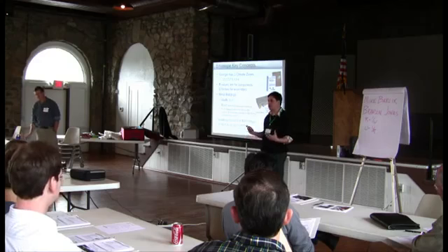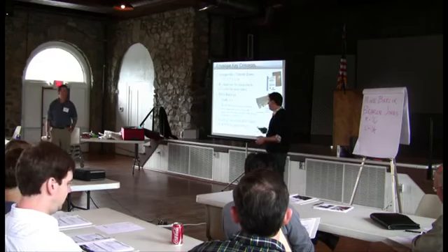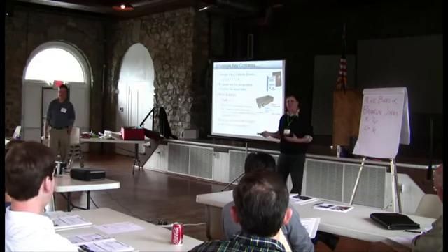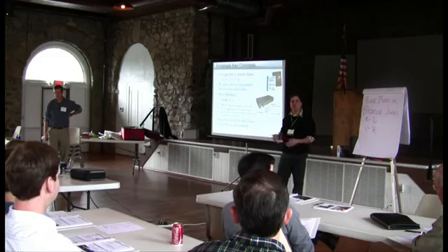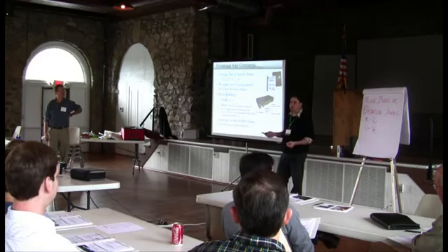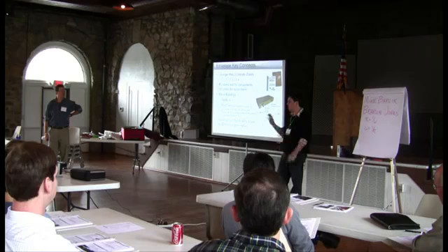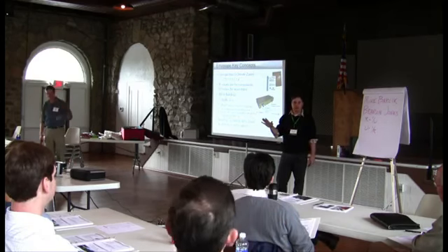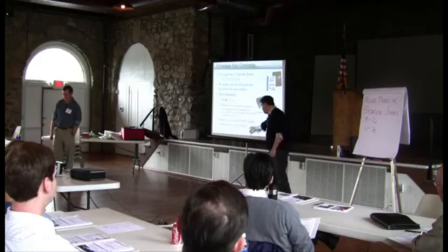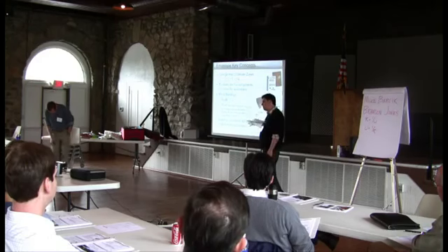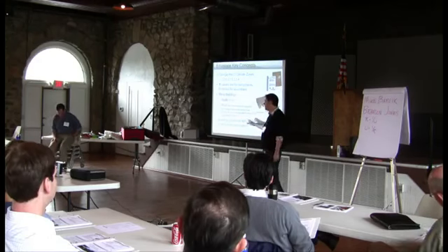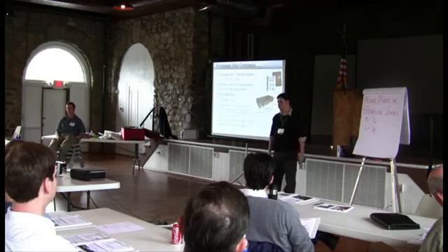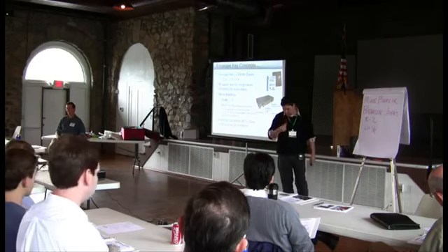So if you're going to build a glass box, we talked a little bit about this energy cost budget method, building simulation. You're going to have to go that route to show that you meet code. You can also have up to 5% skylights as a percentage of your roof area. So if you're going to build a glass box building, you're going to get kicked out of the prescriptive code. Don't do that. Don't build a glass box.